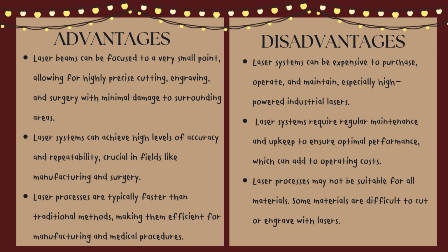Next, we will discuss the advantages and disadvantages of the laser. First of all, we look into the advantages. Firstly, laser beams can be focused to a very small point, allowing for highly precise cutting, engraving, and surgery with minimal damage to surrounding areas. Taking an example, in manufacturing of microelectronics, lasers are used to precisely cut and drill tiny holes in circuit boards with accuracy down to micrometer scales.